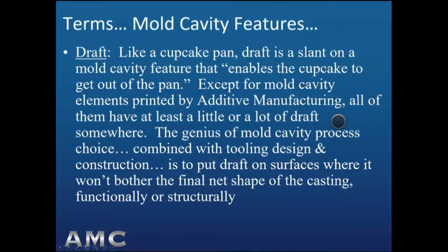Draft. Like a cupcake pan, draft is a slant on a mold cavity feature that enables the cupcake to get out of the pan. Except for mold cavity elements printed by Additive Manufacturing, all of them have at least a little or a lot of draft somewhere. The genius of mold cavity process choice,